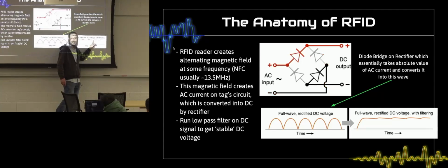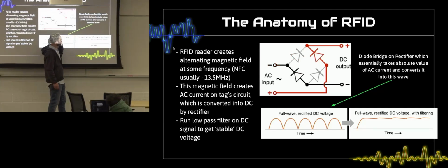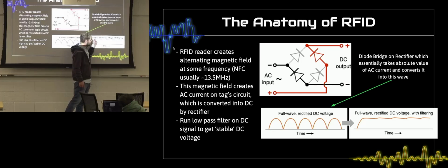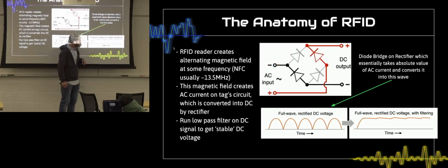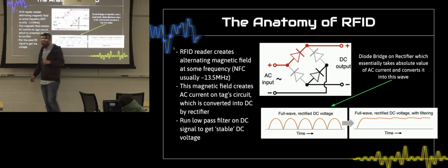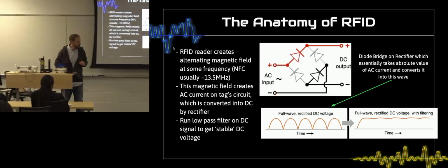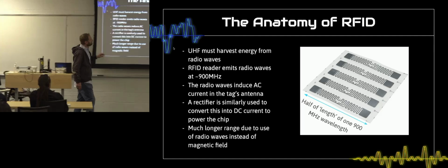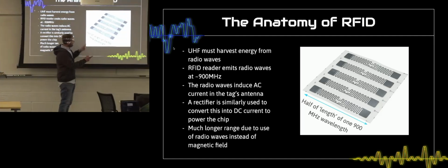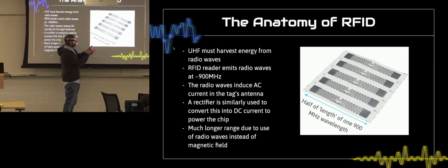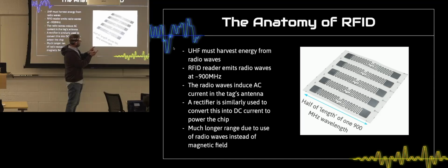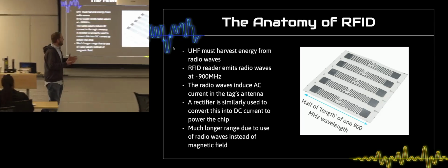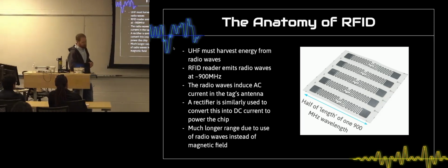It's not a lot of power that's coming through here. This is going to be, in this case, maybe a milliwatt at the very best, but more like 100 microwatts is pretty reasonable for some RFID tags, but it's still usable. And then far field RFID tags. These are about this length. That happens to be half of the wavelength of the wave propagating through space. And there's a tiny little piece of silicon. And this is the one that can be read up to 10 meters or so.